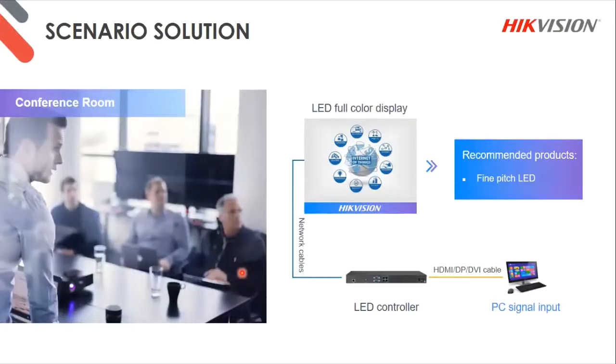Okay, scenario solution. LED full color display. This is for your conference rooms and so forth. You're going to need your fine pitch, like I said, anything less than 2.5 millimeter pixel pitches for your conference rooms and control rooms, along with your LED controller with the inputs, HDMI, DP (DisplayPort), or DVI input signals from your PC. So this is typically a scenario for your conference rooms and control rooms.